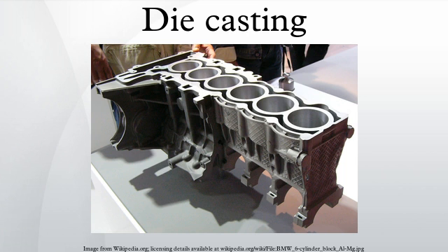Heated manifold direct injection. Heated manifold direct injection die casting, also known as direct injection die casting or runnerless die casting, is a zinc die casting process where molten zinc is forced through a heated manifold and then through heated mini nozzles, which lead into the molding cavity. This process has the advantages of lower cost per part, through the reduction of scrap and energy conservation, and better surface quality through slower cooling cycles.